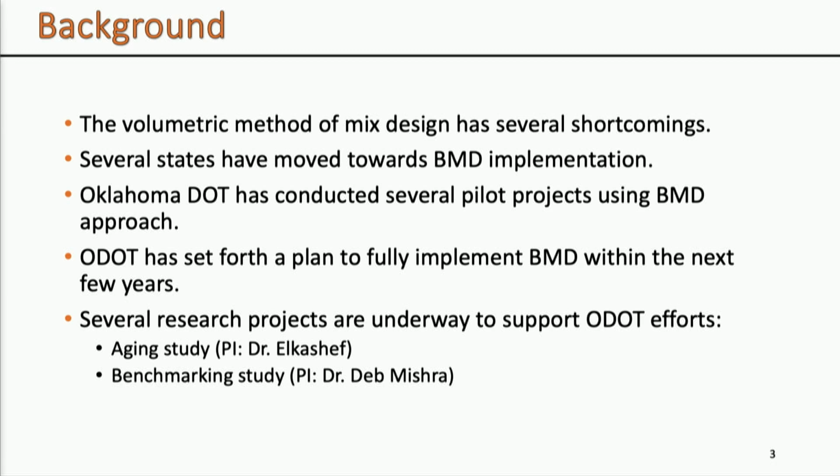So if you know about asphalt, you know that so far we've been using volumetrics to design asphalt. And as strange as this may sound, this is what we've been doing all these years. I mean, we're just looking at air voids and using air voids to determine how much binder we need to put into the mix to get good performance. But we never really looked at performance itself. So we never looked at a test to characterize performance.